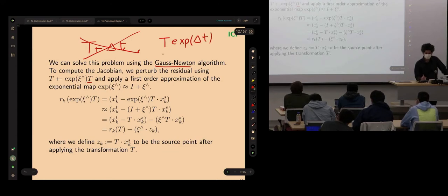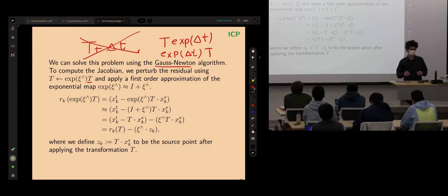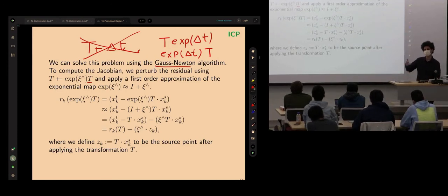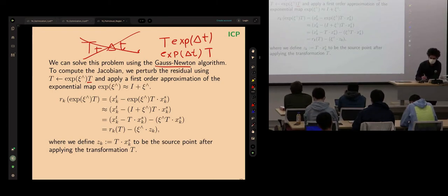Now, in the context of optimization, you're welcome to use both left and right. But stick to one. Pick one and just be consistent. Don't derive the Jacobian using left or right, and then later in your algorithm, you're integrating using the other one. That's not recommended. You might come back and say, oh, look, it's working. But it's not correct, obviously. So we can use some simple algebra to derive the Jacobian. There's no need for calculus.